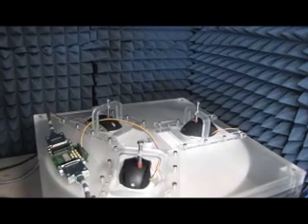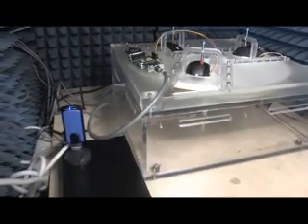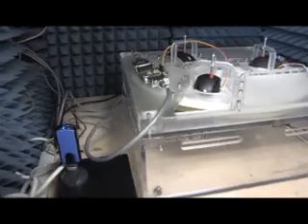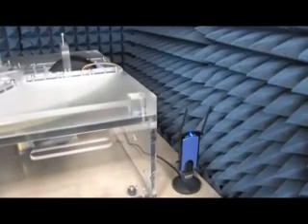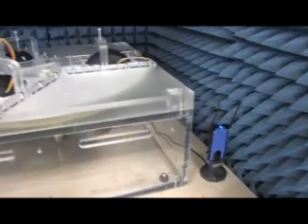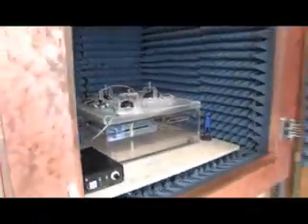Off into the corners of the chamber, you'll see a couple little blue wireless devices. They're Wi-Fi devices, and we use that to create an interference while we're doing our testing. So what we'll do is we'll transmit a large data file from one of the Wi-Fi devices to another, and that's our interference source. So once I turn on everything, we are going to be measuring the data from one of our mice, and we'll be looking at it in the presence of Wi-Fi interference and interference from two of the other mice. So why don't I give you a demo of that?